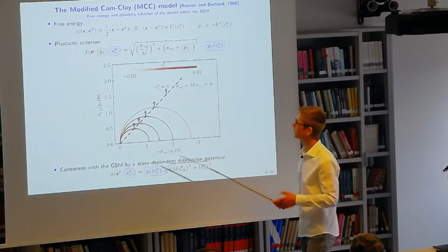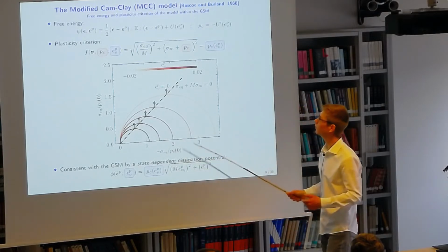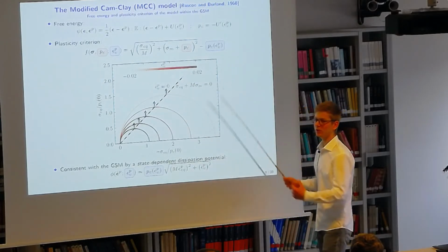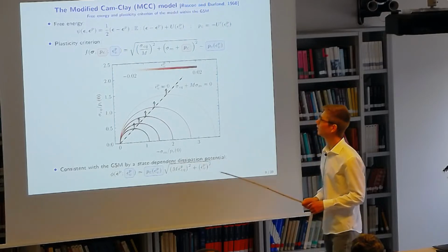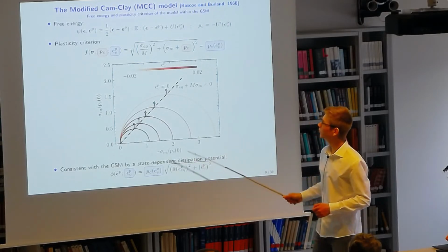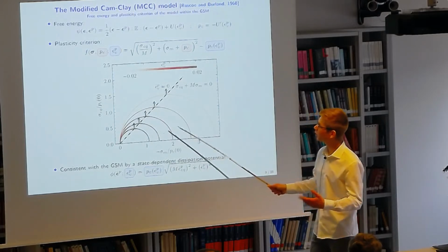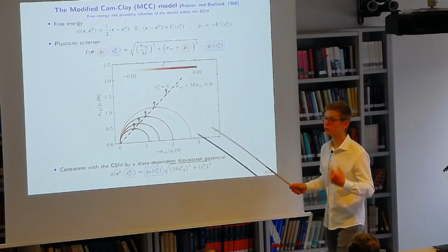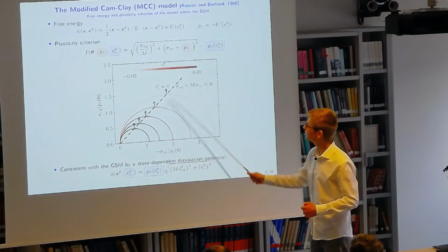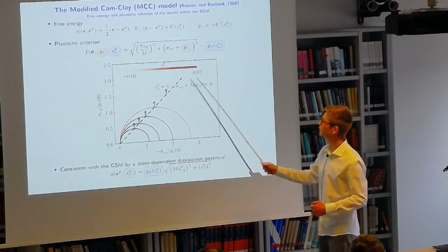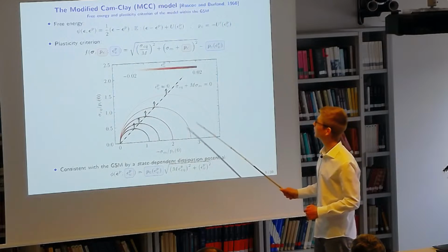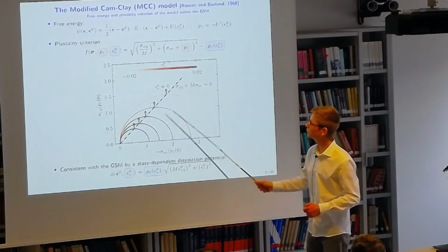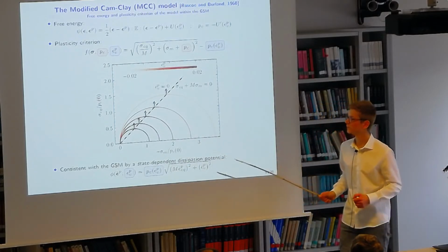The combination of these two is reflected on this figure for different values of the volumetric plastic strain. The more it increases, the more there is a shrinkage of the domain of reversibility. One state of particular interest is the one which is located at the top of the ellipse, which, according to the flow rule, which is normal, predicts isochoric plastic flow. At this stage, you have a linear combination between the equivalent stress and the hydrostatic stress by a friction coefficient named M. In the context of granular soil, this one is so-called the critical state.